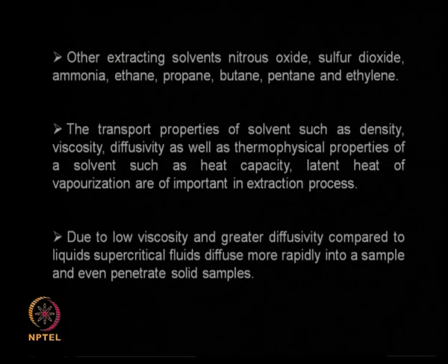Sometimes other solvents are also used for supercritical process, like nitrous oxide, sulfur dioxide, ammonia, ethane, propane, butane, pentane and ethylene and so on. So the transport properties of solvents such as density, viscosity, diffusivity, thermophysical properties, heat capacity, latent heat of vaporization, all these are very important in an extraction process.